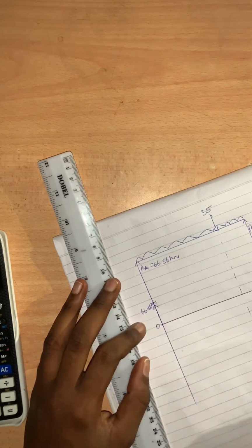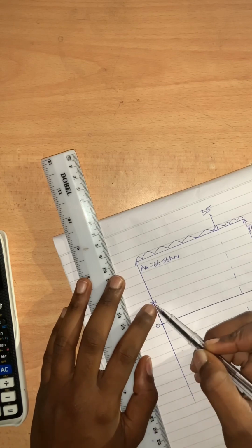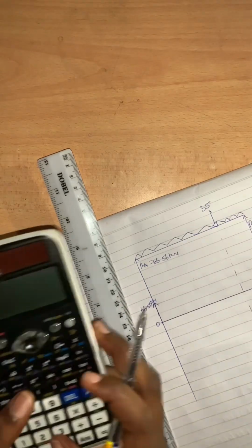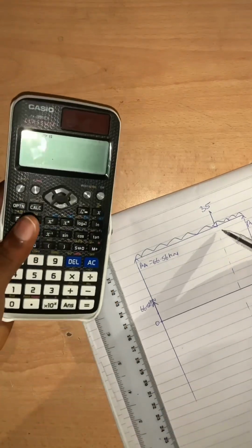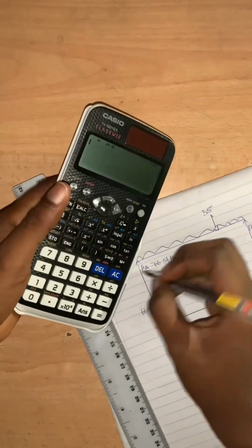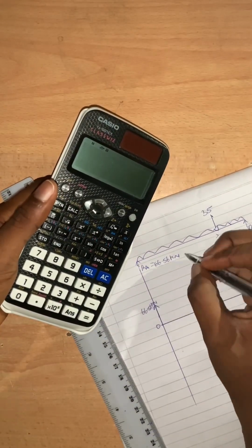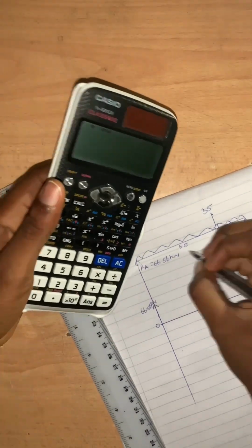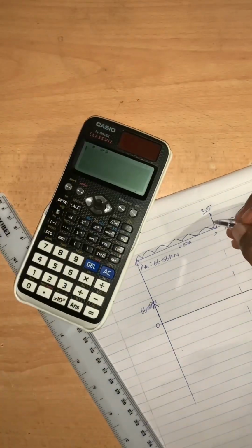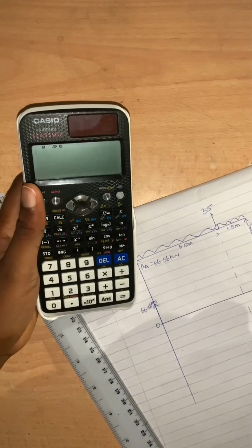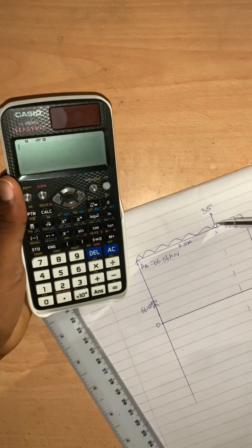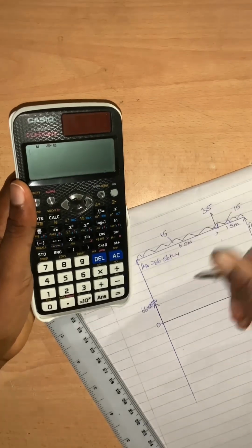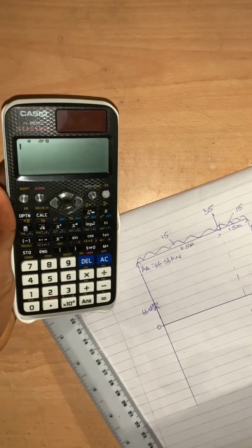So we have this going up by 66.56 kilonewton, and then at this point it also encounters a UDL, so it is going to slope down. The UDL is 120, so you would go down by 120, but you're not going to make that mistake. From here to here is 6.5 meters, and from here to here is 1.5 meters. Because you have this 35 kilonewton in the middle, there's going to be a shift in the shear force diagram. So what you are meant to do is split this UDL. Although this part is still 15 kilonewton per meter, and this part is still 15 kilonewton per meter, the distances are different, but it is actually the same thing. We are just splitting it in half.